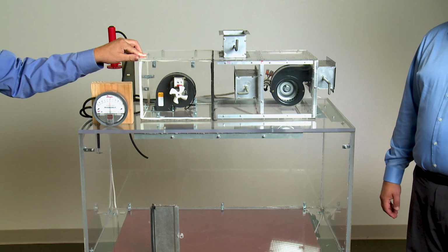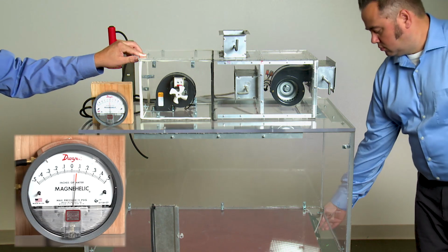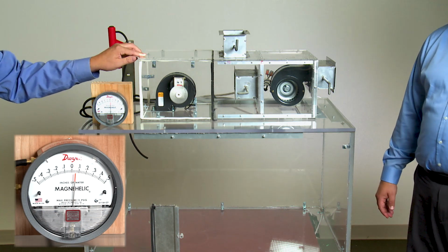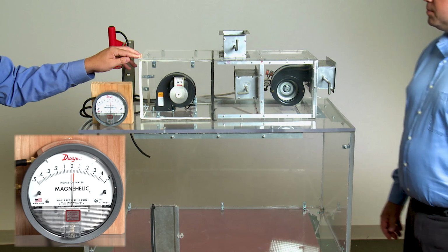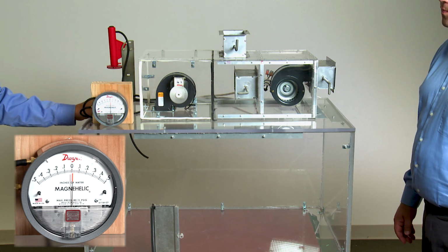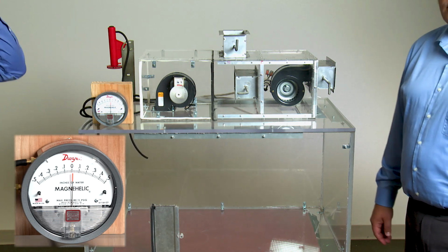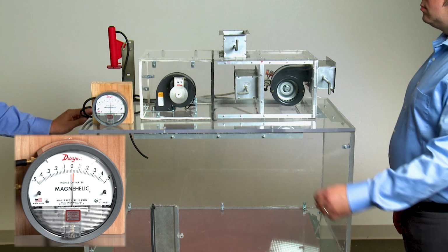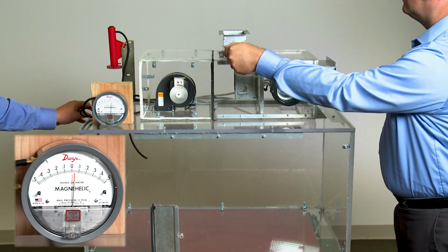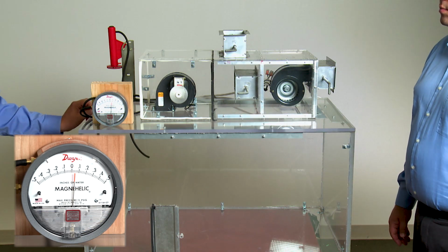Let's demonstrate the on-off control method for this relief fan, which Chris just introduced. We turn on the supply fan, and Eric has the damper set again for recirculating only mode. Note that I relatched the barometric relief damper in this side of the building, so it won't open for any of our remaining demonstrations. As Eric opens the outdoor damper to minimum position, again, building pressure rises a bit. The relief fan is still turned off, so we're just relying on natural relief so far.